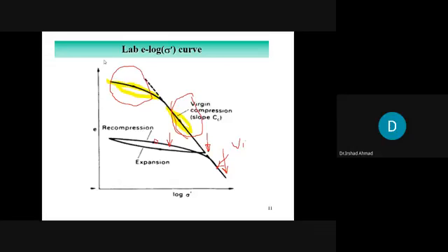Now, the current state of stress in the soil is less than the past one. If you take that soil specimen and bring it to the lab, and you start the test and apply stresses, and these stresses are less than the ones imposed 100 years ago by the fill material, you will have a curve portion, right? But by the time that maximum stress level is exceeded, it will linear out. You will have a virgin compression curve. Now you understood?